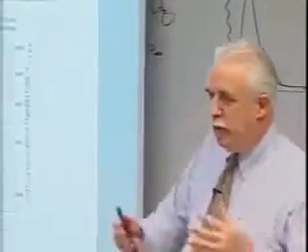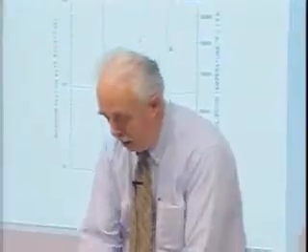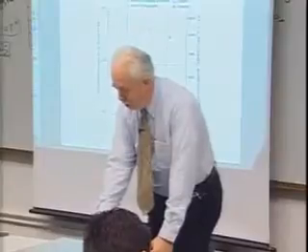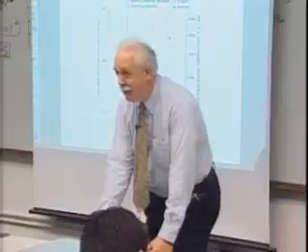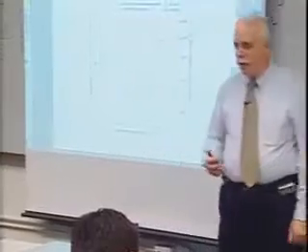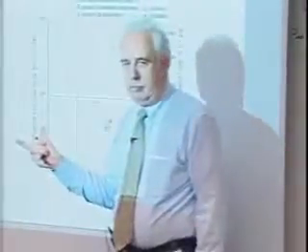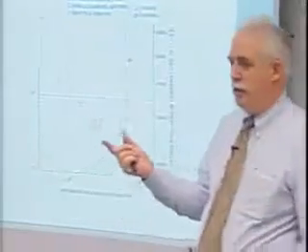What was wrong is we didn't have communication with all these people. Somebody gives me a trajectory and I calculate heating. And I say, boy, this is what I think it's going to be. And I'm going to show you some of that in all honesty, which you won't see in journal articles. But I better put a little bit of pad on that because I don't know this that well. You put all those things, they compound. We call it compound conservatism. Everybody puts their 10% in and you get your factor of 2. Now, you just lost significant, if not half, the payload on the shuttle by doing that.